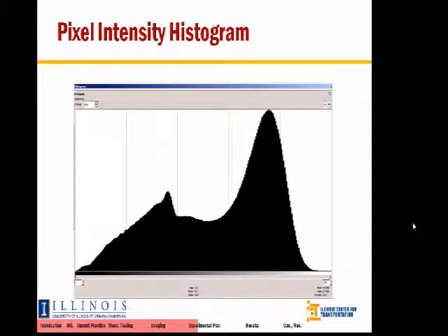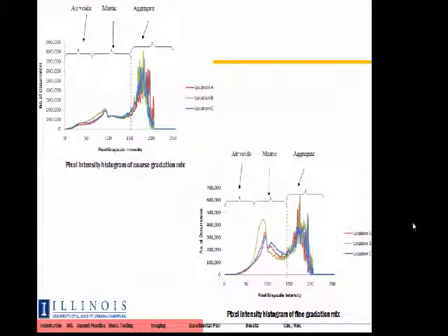This is a very common pixel intensity distribution for HMA. Proof is right here. Okay, 2 different plots, one for the coarse gradation, one for the fine gradation, and an image from each of the 3 locations. So just so it doesn't get too cluttered in doing 6 images, it's showing 3 in this case. So location A, B, and C as the physical slices were referred to. We see that same general shape of the pixel intensity distribution.